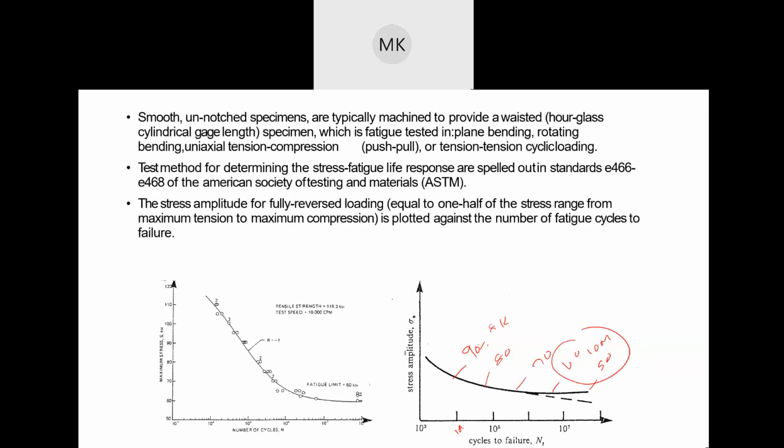So if that's the case, then I would start doing 62, 65, 72, 82, all these things for me to understand the entire growth. And the graph would finally look something like this, where I'll have very low life at high stress, and as I reduce the stress the life keeps going up, and then at one point it will flatten out, and that flattening out tells me that this material is a mild steel, or a BCC material which has lower hardness and good strength,